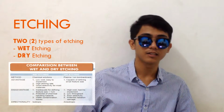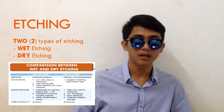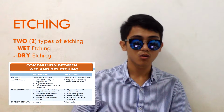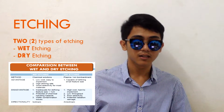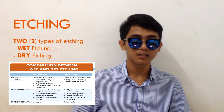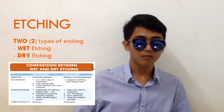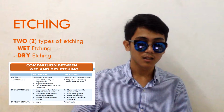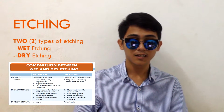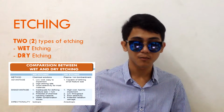Comparison between wet and dry etching. Method: for wet etching, chemical solution; for dry etching, plasma and ion formation. Advantages of wet etching: low cost, easy to implement, high etching rate, and good selectivity for most materials. For dry etching, it is capable of defining small feature sizes. The disadvantages for wet etching are the potential chemical handling hazard, and for dry etching, low throughput, low selectivity, and potential radiation damage.